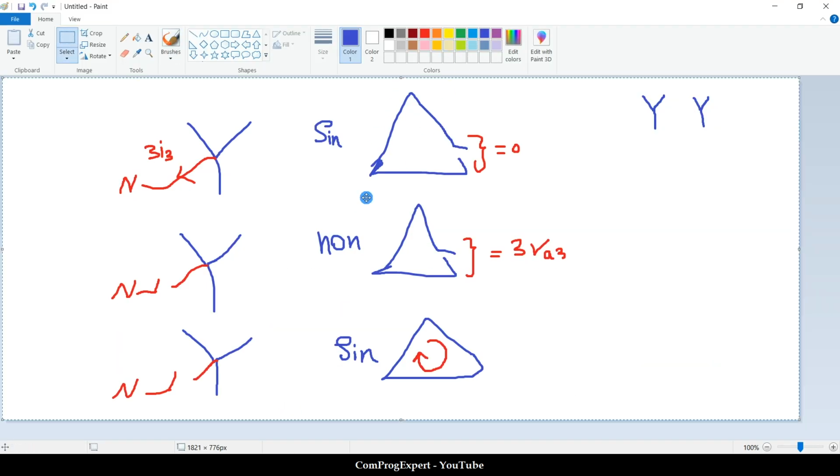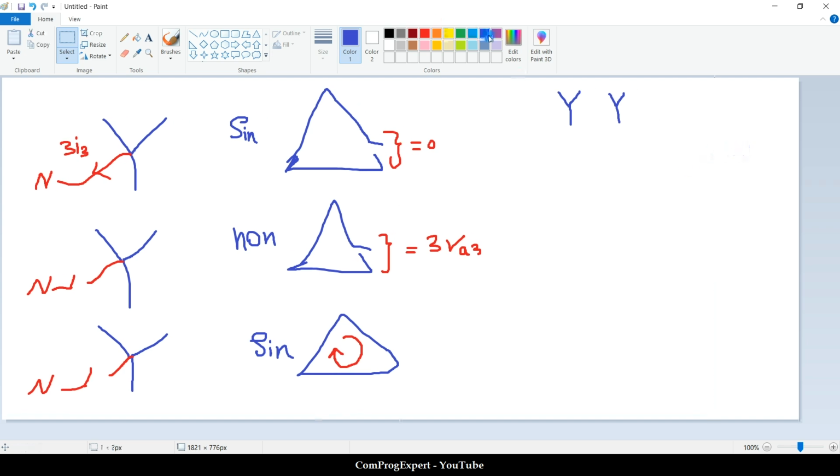If we have to use this transformer Y configuration, we can have 3 sets of coils. So connect the load here to this set of winding, and also we can have another delta winding for the third harmonic, to have this third harmonic current in it.